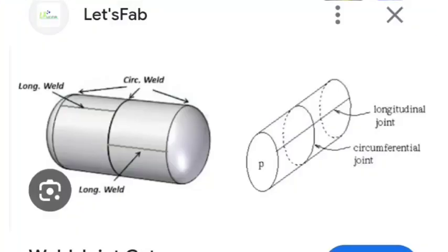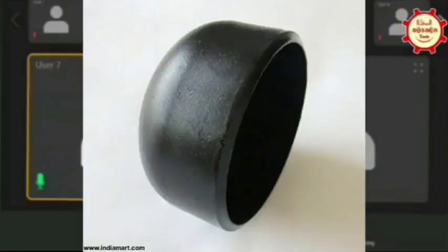My question, shall I ask again? Yeah, please. We have one shell with two ends, but it's a seamless pipe, because one circumferential seam will come for internal assembly purposes. But both shell end connections are standard pipe caps, which are seamless. So for the shell, long seam 0.85, even though it's seamless, as well as the circumferential seam, 0.85, because one circumferential seam is coming now.